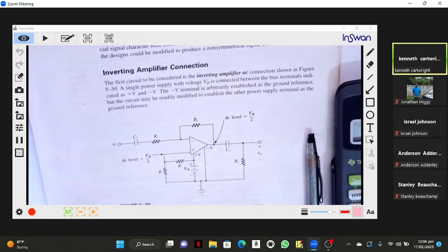I didn't ask anybody in the magnitude plot to mark your frequency and dB. I asked nobody to do that. What I actually asked was to mark the -3 dB point. The -3 dB point is what I asked for. You don't listen carefully and you don't read carefully.